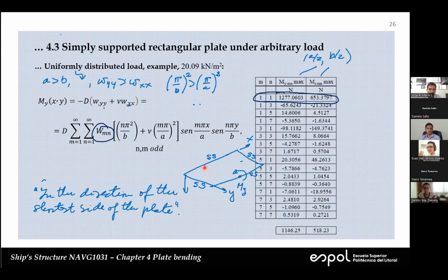On the top surface, you're going to have positive or negative stresses on the top. Mr. Ramirez, no, I asked Mr. Pesantes, on the top of the surface, you're going to have positive or negative stresses here? Mr. Pesantes? Is positive. Do you agree with that, Mr. Romero? Positive or negative? I think that is negative because it's a compression surface. Yeah, it's considered compression. You have forces like this, so on the top is going to be compression, on the bottom is going to be in tension.